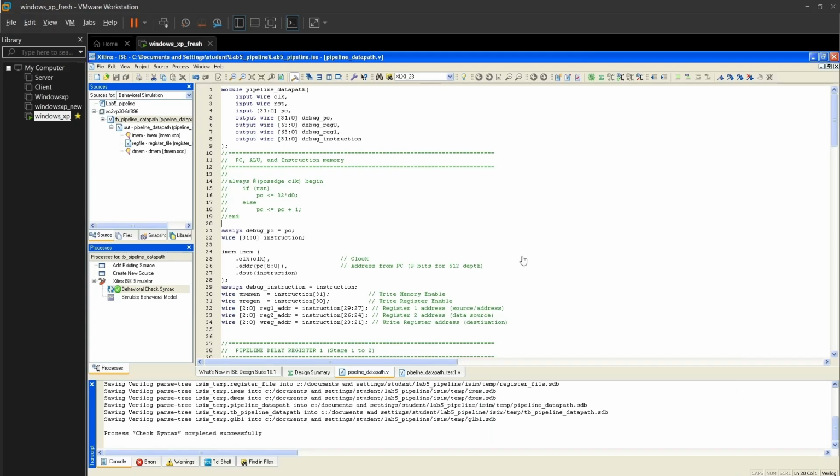The previous sim was not practical enough for a NetFPGA application. While checking on a NetFPGA, it would be hard for us to exactly see what the values are at any particular clock cycle, because the whole cycle is done within about six clock cycles. We won't be able to see and track which instruction is going on, or what register value we're getting for our small test bench case. So we made a small modification to the other code, which is giving a PC as an input value.